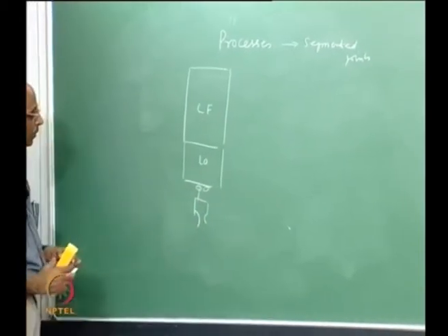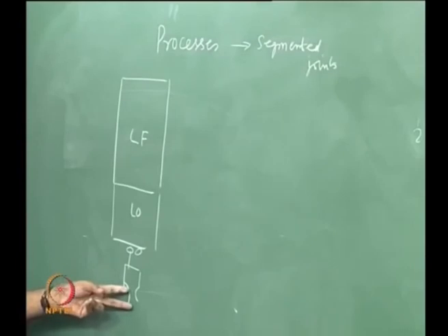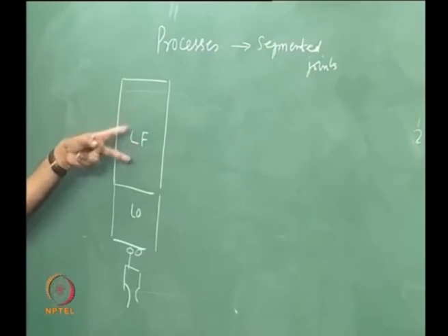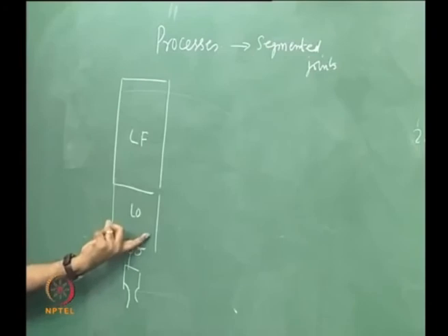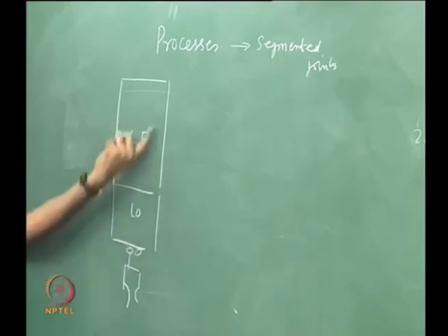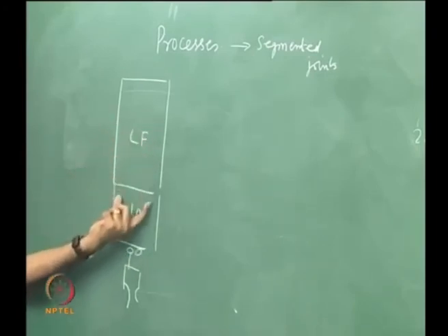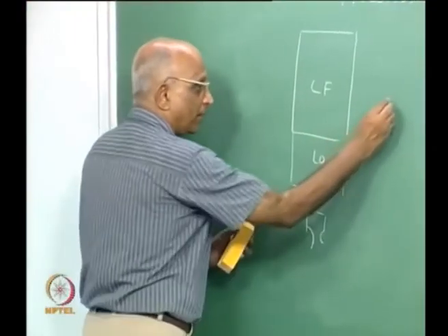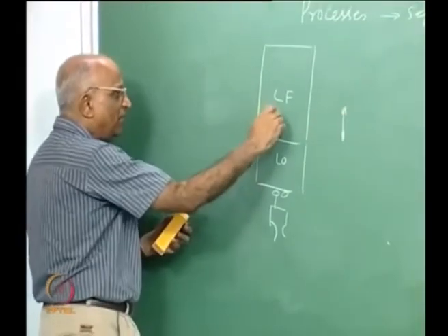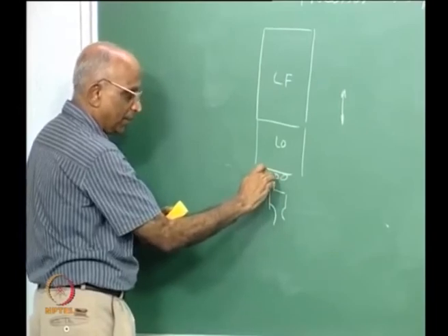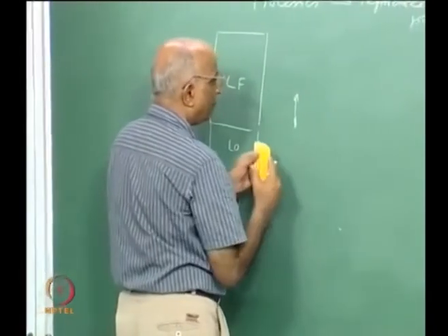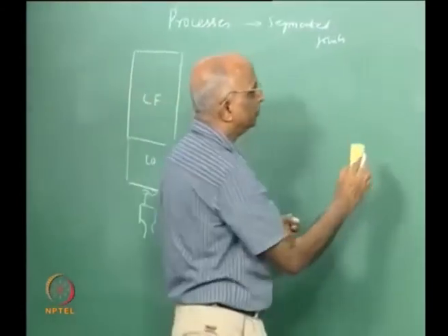Now let us say under certain conditions, when the thrust is generated, I have the head of the propellant over here, and these are all columns. The tank can vibrate in the normal direction, it can oscillate up and down, and when it vibrates, the head of the fuel available at the pump inlet changes. Let me draw a schematic diagram.